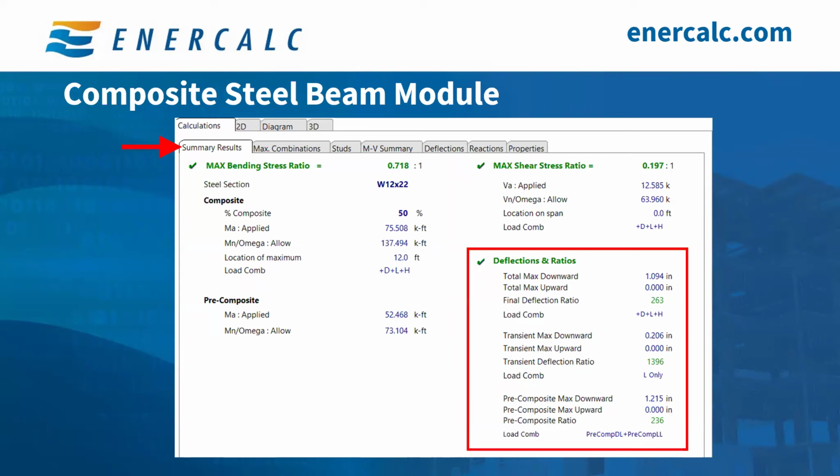And I think I want to dive in a little bit here to show you the different things that we do. So the first set is the total maximum deflection. This includes the deflection that occurred before the full composite action has been achieved. That means whatever permanent deflection occurred on the beam by itself before the composite action has been achieved, that is additive. If the load is remaining, such as self-weight, that would be additive to